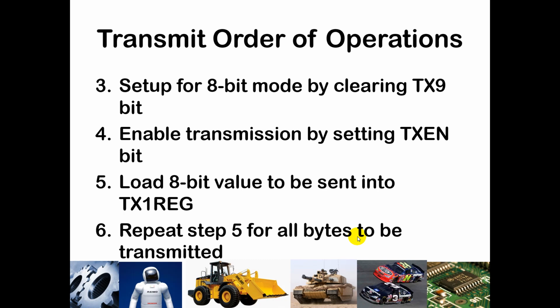And then once everything is set up, you can simply just keep putting in the values in TX1REG 1 byte at a time as you wish to send those on out. And so you will just send and send and send for all of the bytes that you wish to send. Now it's important that you pace these things, so you can either watch the flags to determine when things are done, or you can put in a delay and just make sure that you're waiting long enough between transmissions that you don't have a problem.